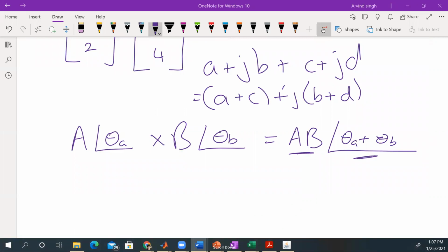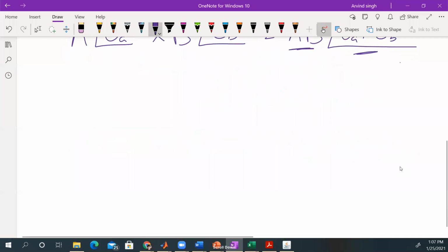Now, sometimes people have difficulty sketching phasors, and I have no idea why, because literally all you are doing is drawing the line at the angle. So we start here. 0 degrees is considered to be in this direction, and then we go anti-clockwise.